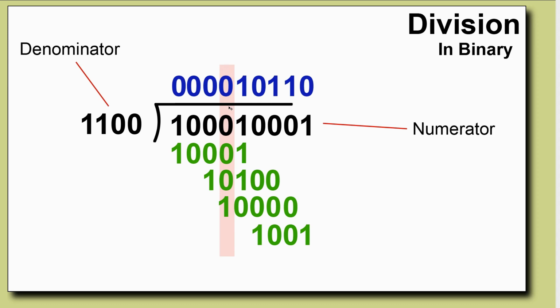Now, in the pipeline CPU, the registers are 8-bit. So rather than doing a 16-bit shift operation to pull off 1 bit at a time, we just need to look at a single 8-bit register. And then when we're done, it's the same as when we moved from this bit to this bit. We just move from 1 byte to the next.